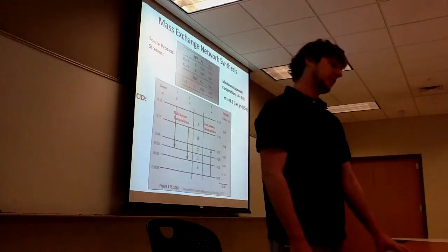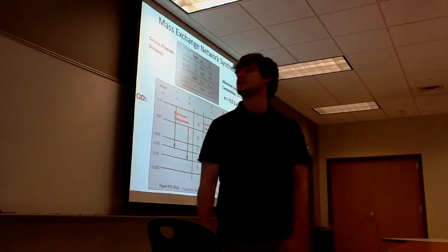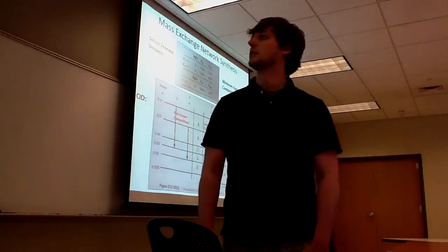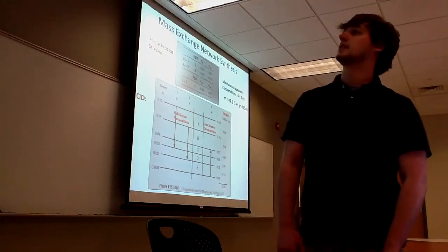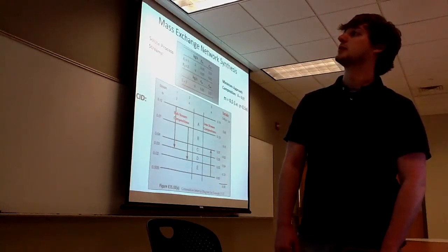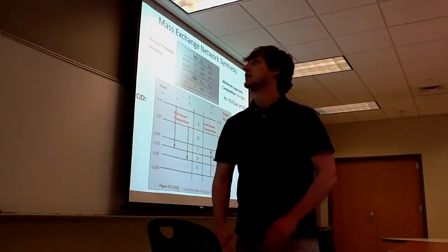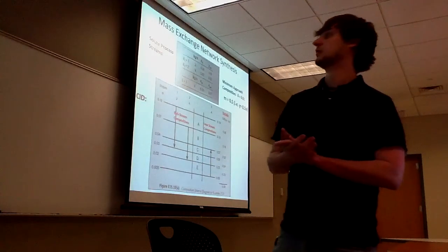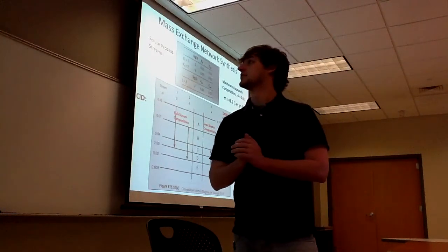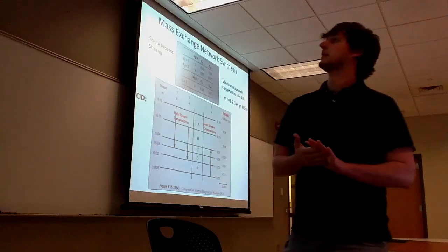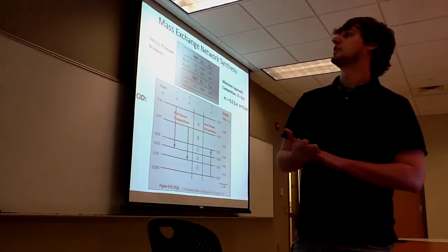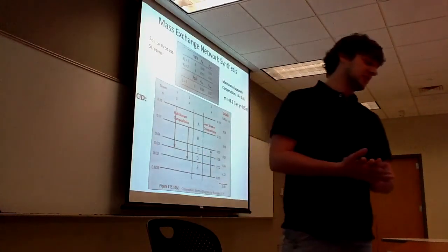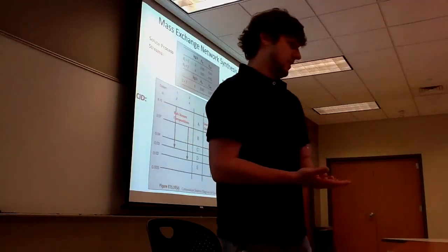To cover this a little bit better in mass exchange networks, we're going to involve a synthesis problem. First, you have your process streams. Lay those out with, again, R as your rich stream mass flow rate. And of course, this one we have 3 streams. And given in the problem, we have our minimum approach composition of 0.01. Also given is the physical parameter of the partition coefficient, which is 0.5. And then we have our composition interval diagram.